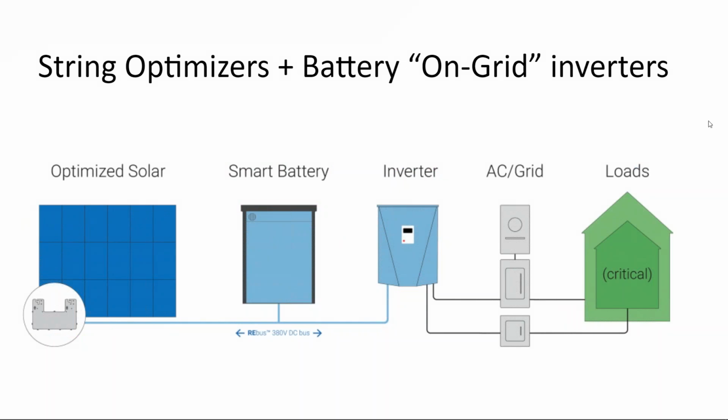And so I kind of like them because they've got one optimizer for the circuit rather than for the modules. They also have the option between flooded lead acid or a lithium ion battery, and then they have an inverter that's designed for the optimizers, which is a little bit cheaper than one that can take variable voltage. Now what I would say is even though technically their cost should be optimal, the size of the company means that it's not. They're a startup, whereas others are not.